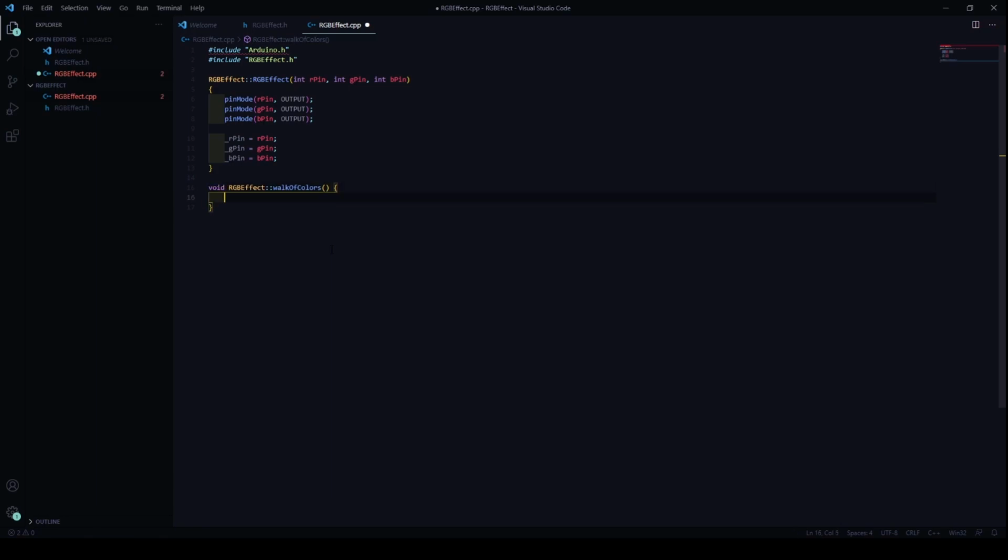So what we are going to do is we will start with one color and move till, with one color, like we are going to start with a value 0, 0, 0 for all these pins, and then we are going to write it all the way up to 255, 255, 255, and for that we are going to use the analogWrite function. Let me quickly write this code, then I'll explain it, or I'll just write the command.